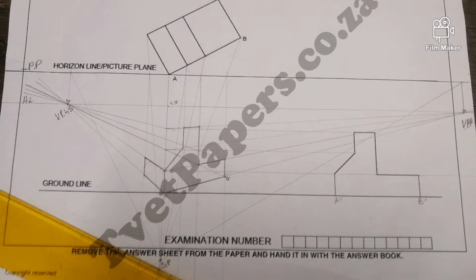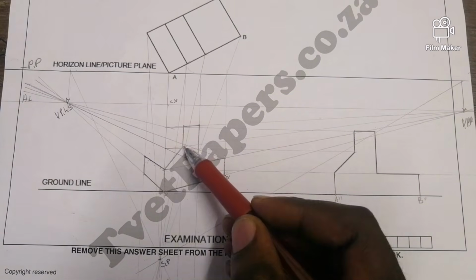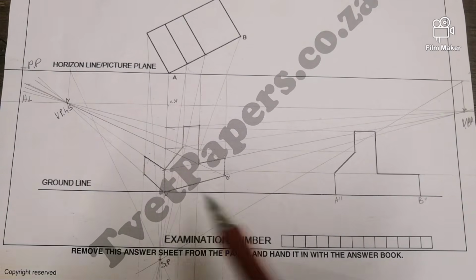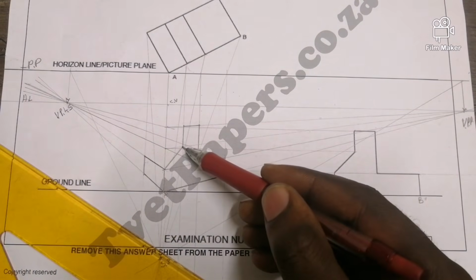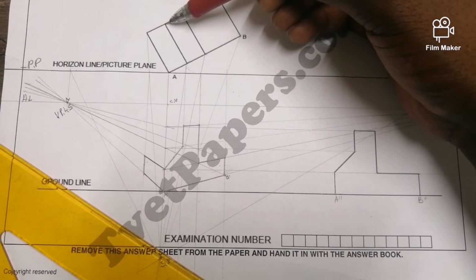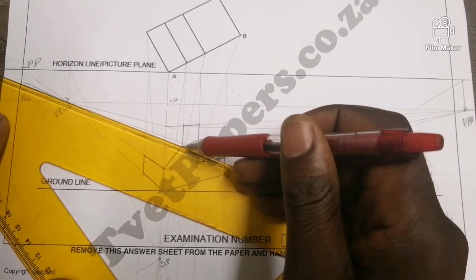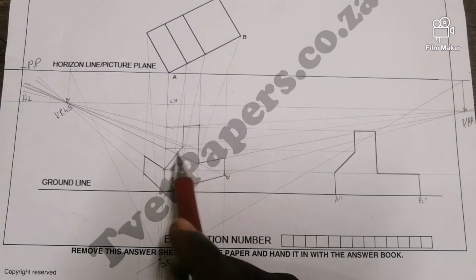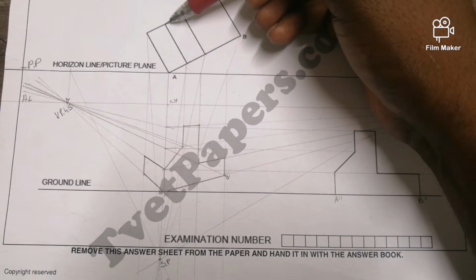Then from there I am going to get a point somewhere there. So you have to take this point to vanishing point of your left hand side, this one. So if I take this point to vanishing point of my left hand side, it's good as if I'm moving from here to this point that I'm looking for. You understand? So take it. There you go. So along this line, I must get to that point. So the point that I'm looking for is this one.